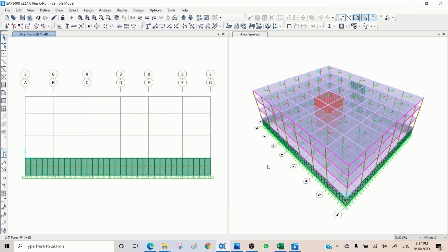So this is video 1 of module 3. We simply just define lateral stiffness for the retaining wall, and we use simple rigid or pin connection for the columns. In the next video, I will show you how to define the foundation and how to create a model for pad footings and how to apply a spring stiffness for foundation.